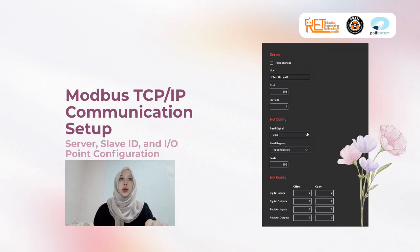And also there are the digital outputs, where the offset is set as 0 and count 2. This is the range for the two conveyor motors, the buffer and the entry conveyor, since these are the outputs of the PLC that send commands through, starting right from coil 0.